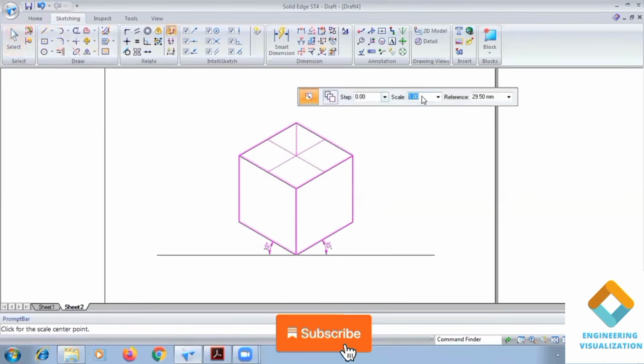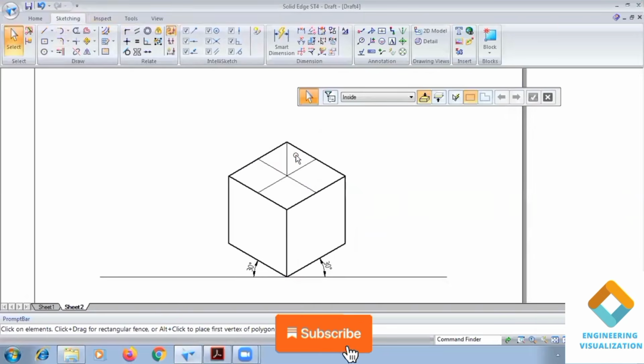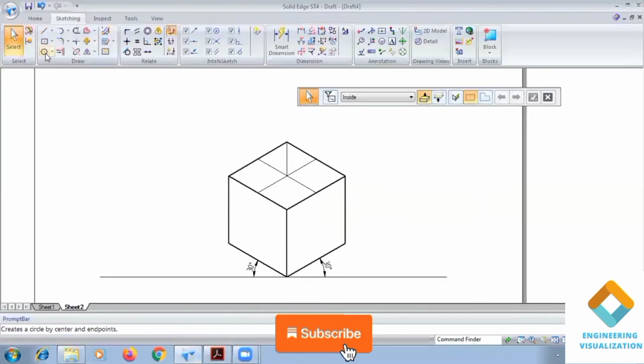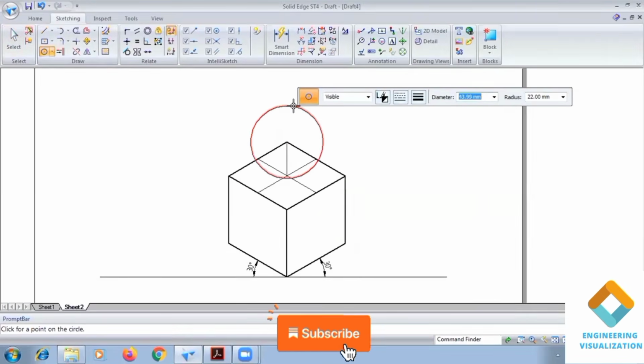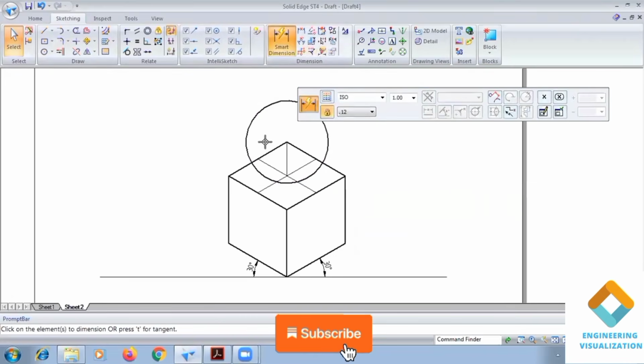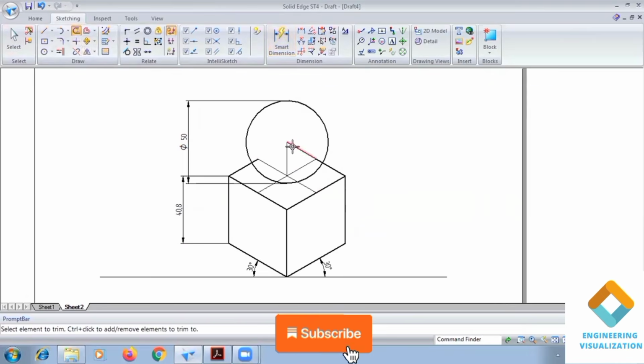Go to scale here, type 0.816 or 0.823, you can type it. Now go to circle and draw here, that is the center of the sphere. Now draw a circle of diameter 50. Enter. So that completes the sphere. So always remember, the sphere will be drawn with the actual scale, other solids will be converted into iso. You can check the dimensions here. This sphere is 50, actual dimension, but if you check the dimension of the cube, it is less than 50, because after converting to iso it is converted into smaller dimensions.